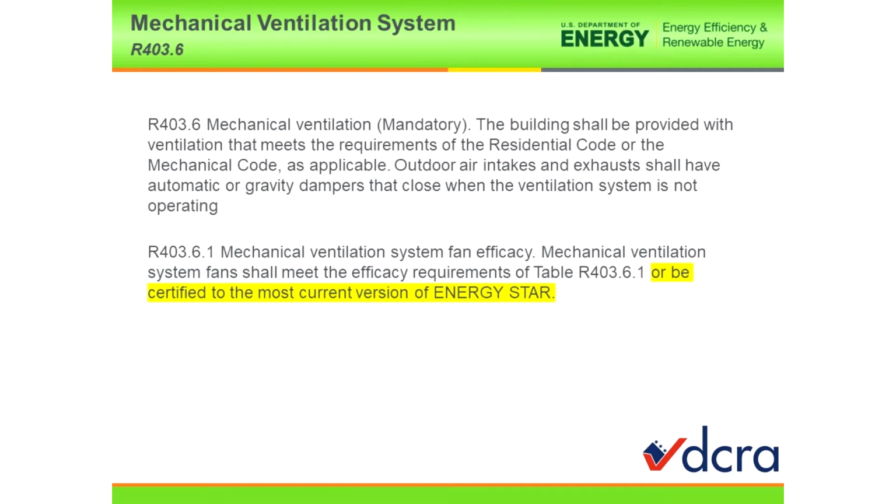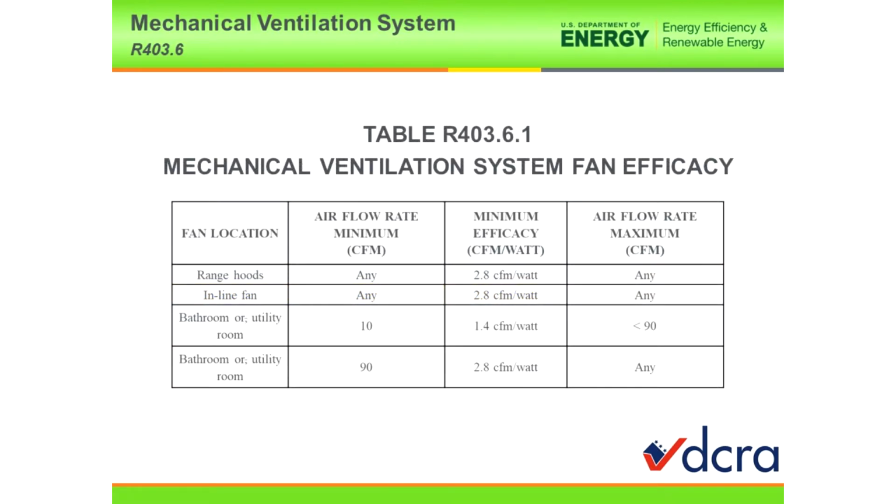Mechanical ventilation fans shall meet the efficacy requirements of Table R403.6.1 or be certified to be the most current version of Energy Star. Now here's what you guys do. You show us this slide. Just in case you didn't know, we know this slide, okay? So showing us this slide does not meet compliance. You have to tell us how you meet compliance. So we have to see the CFMs and the wattage data for your fans.